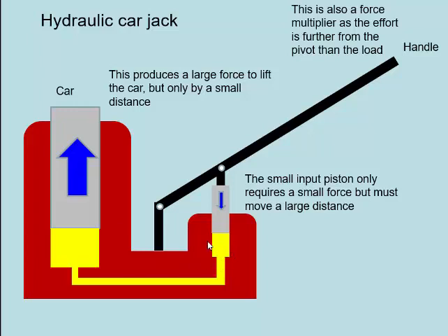In reality, there's also an oil reservoir in here. This is an oil that passes through from the small piston to the large piston, and so what the mechanic would have to do is push the handle down to raise the car a little bit. As they raise the handle back up again, this would again fill up with oil, and they could pump the handle several times to raise the car a few centimeters for them to work on it.